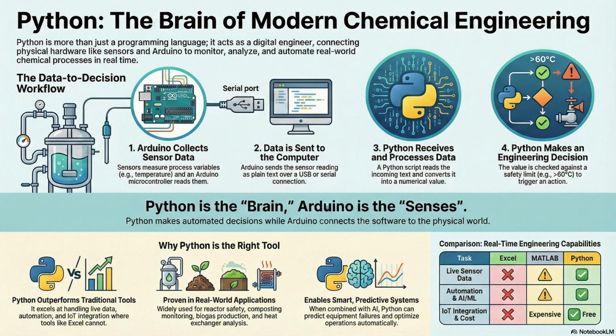What are the biggest advantages of these smart systems for an engineer? I'd say there are three huge ones. First is predictive maintenance. The AI can detect the early signs of fouling or bearing wear weeks before a catastrophic breakdown. Second would be abnormal pattern detection. Yes, this is so important. The AI is much better than simple stats at spotting subtle correlations, like a tiny drift in pressure at the same time as a tiny drop in temperature. It sees the ghosts in the machine that signal a sensor is failing or the process is becoming unstable.